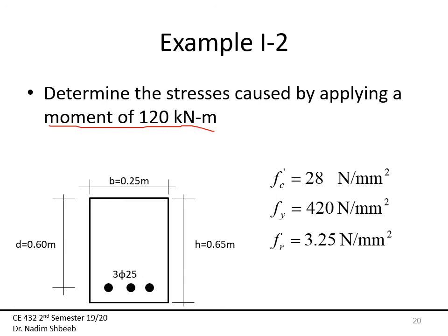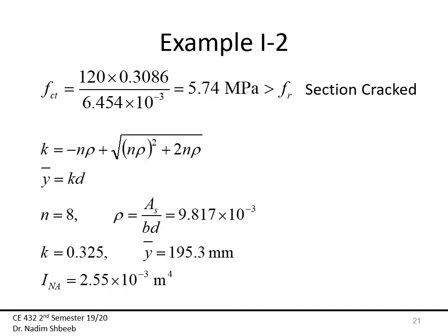Okay, again, if I go to this example beforehand and I have not done the previous one, I have no clue if the concrete is cracked or not. So the only way for me to know if it's cracked or not is to find the stresses in the tension fiber first, and then make the decision whether it is cracked or not cracked. And so that's what I'm doing.